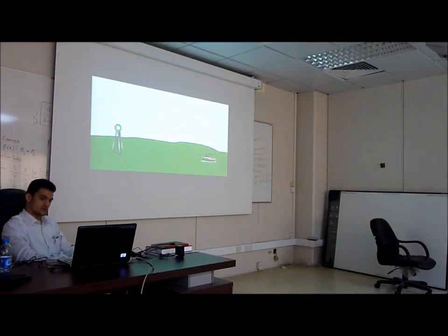To solve this problem, we use the Doppler effect, which is the change in frequency of the radar wave when it encounters a moving object. When the pulse hits the stationary tank, it reflects back at the same frequency. However, when the pulse hits the jet as it is moving away, it reflects back with a lower frequency. Finally, as the jet returns, the pulse is reflected back with a higher frequency because the jet is moving towards